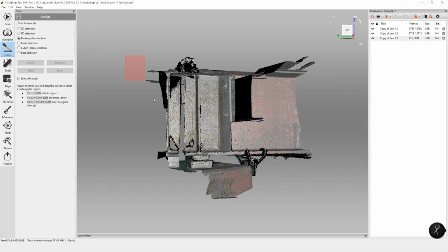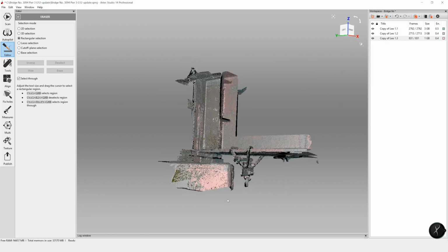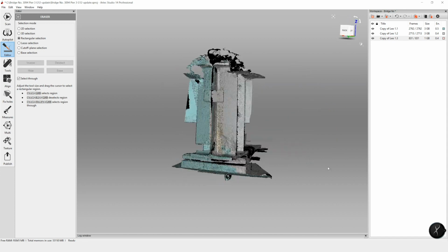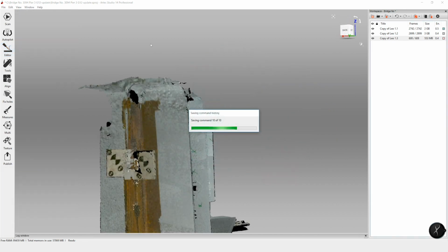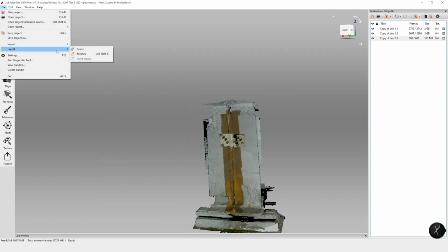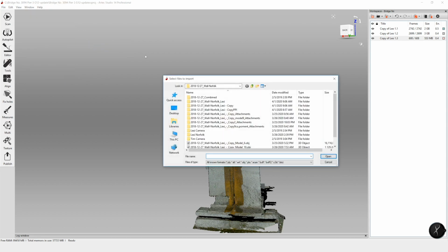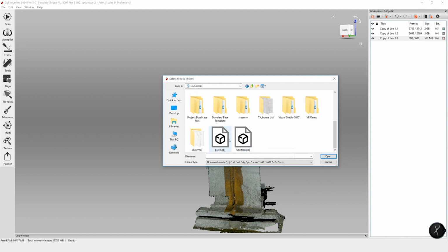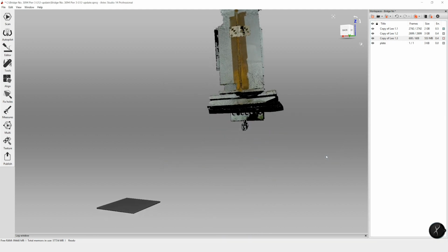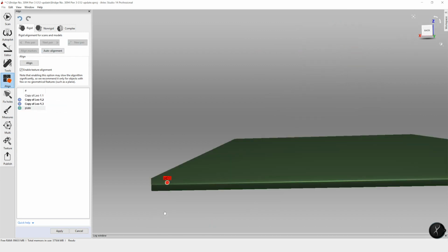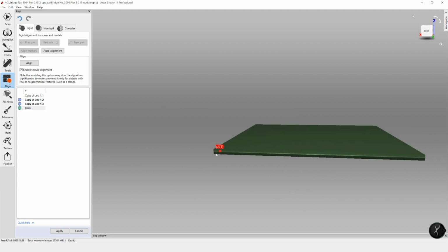Once we've deleted all those scans, we can move into editing out our extra geometry. You can go through, delete all the extra information that we're not going to use for our alignment. Once that is complete, we can then move into our alignment. And what we're going to do here is bring in an object, such as a rectangle, that has the same thickness as the web. This essentially ensures that when we're lining up our 2 faces along the intact portions of the web, we'll have a known web thickness.